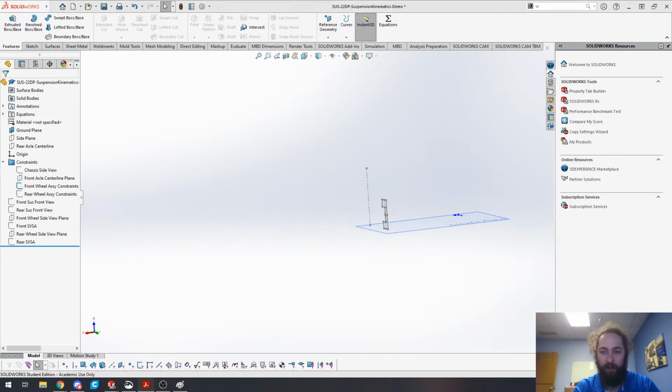There's more outlined within our CVD. I'm going to switch back to that and just pull up a page number real quick. Section 17.5 is what covers front suspension design. Towards the end of that section, starting at around page 630 and 631, is what we're going to be following here. They're pretty confusing. Hopefully working through it is going to make a little bit of sense. But basically they're operating on a couple of geometrical principles, and using that to combine the front and the side views together in order to give us our control arms themselves.